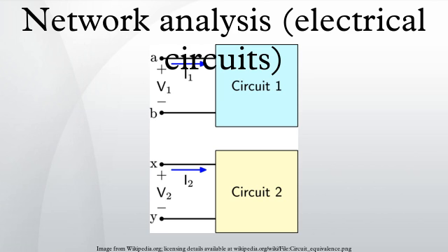A popular form of specifying the small signal equivalent circuit amongst transistor manufacturers is to use the 2-port network parameters known as H parameters. These are a matrix of 4 parameters as with the Z parameters, but in the case of the H parameters they are a hybrid mixture of impedances, admittances, current gains and voltage gains. In this model the 3-terminal transistor is considered to be a 2-port network, one of its terminals being common to both ports. The H parameters are quite different depending on which terminal is chosen as the common one.